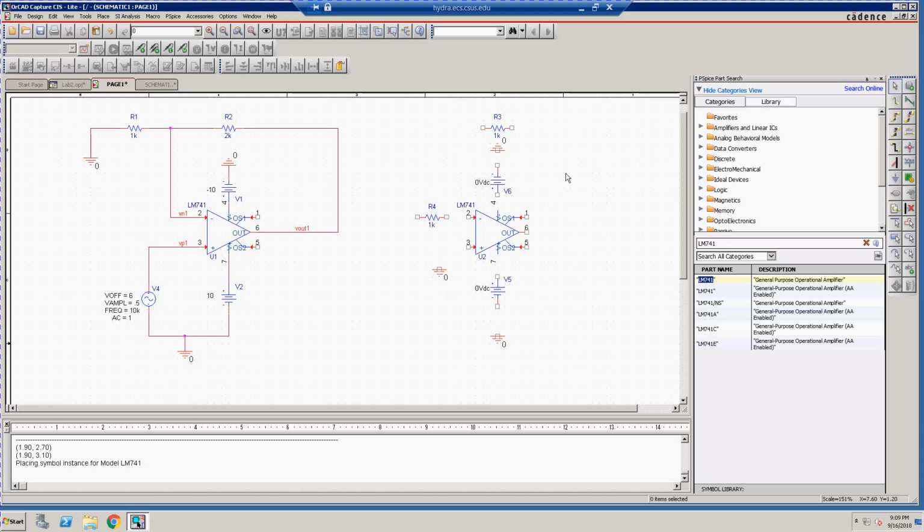Okay, now we're ready to connect everything together with what's commonly referred to as nets, which are just wires. To do a wire, I want to point out you can come over here and there's multiple options too, to place a ground, components, nets, name nets, or wires. The one thing I want to point out here is, for instance, to draw a wire, you could either click on this button for place wire, or you'll notice when it pops up, it has a W in parentheses next to it. That's an indicator of a hotkey or a shortcut. So you can hit W. You'll notice it goes to the crosshairs.